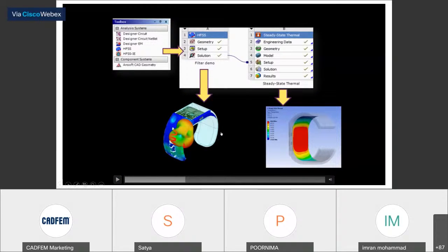Yeah. So while doing the electronics part, it is operating with certain power, but with longer use, the temperature of that device is going to rise. So that's why after doing the HFSS analysis, we have to do a thermal analysis. That's the important part, because otherwise it may give out a burnout. That's why this watch has to go through a multi-physics analysis.